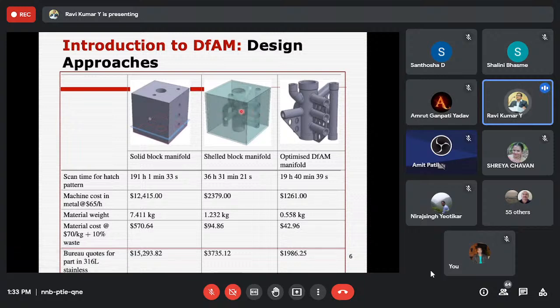While adding the material, let it be as little material as possible, not huge masses, huge bulk, right? But huge bulk may be attractive for CNC. Why? Because if you have more complex geometry, you have huge wastage and huge exponential growth in the cost, right? It's quite a contradicting scenario here between CNC and additive.